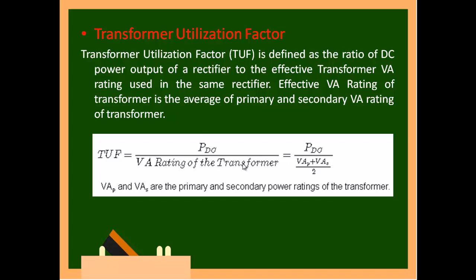So when you put a transformer, you have to decide depending upon your DC requirement. If you require a small amount of DC, then the rating of the transformer also should be less. If you put a very high rating transformer for a small application, source inductance will come into picture, and the source inductance will make the loss maximum, or even the output will be 0.